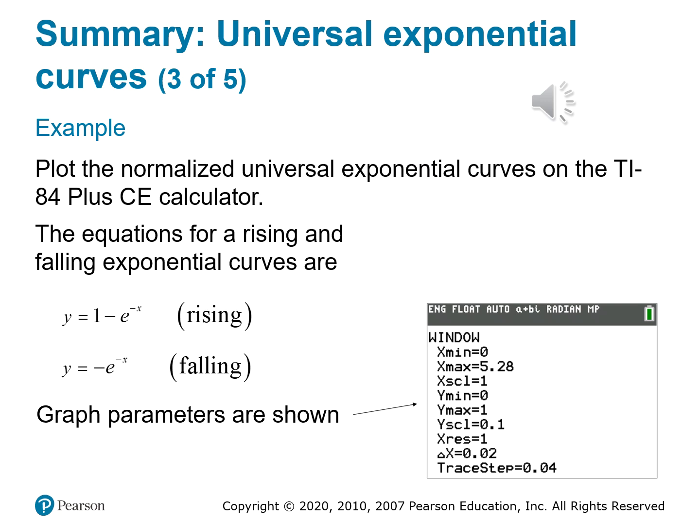So the two normalized equations are the rising exponential and the falling exponential. The rising exponential is the following: y is equal to 1 minus e to the negative x. This models a voltage or current building up over time, like current in an inductor after a switch closure. The falling exponential is y is equal to e to the negative x. This represents a decaying response, like inductor voltage dropping off after power is removed. These curves don't require any specific values for L or R. They're normalized using the time constant. That's why the curve is called a universal.